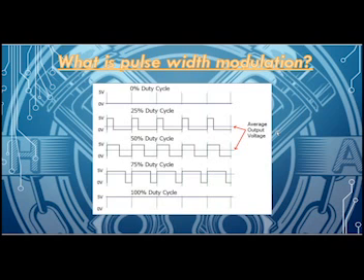So I'm just going to quickly go over this little diagram that I've got here. As you can see, it is a diagram of each pulse width that is being generated. Judging by how many volts it is going up to, I would suggest this is a diagram from a sensor, whether it's an ABS sensor or a cam or crank sensor, because quite often when you are looking at sensors around a vehicle, most sensors operate within 5 volts.